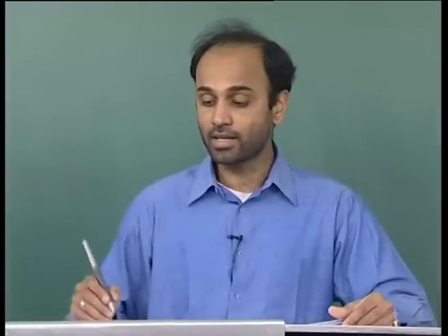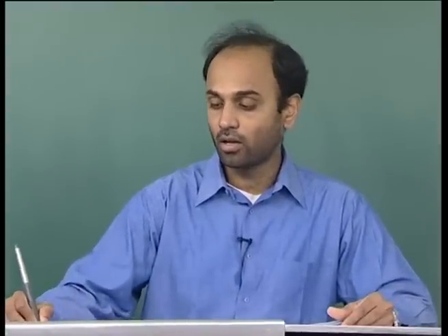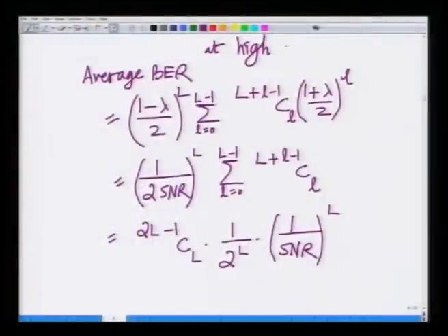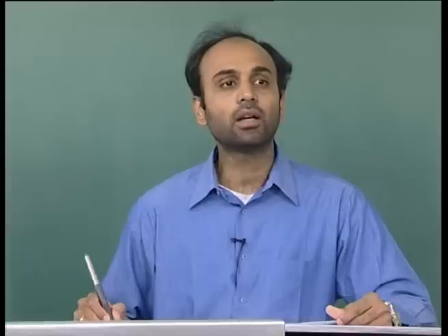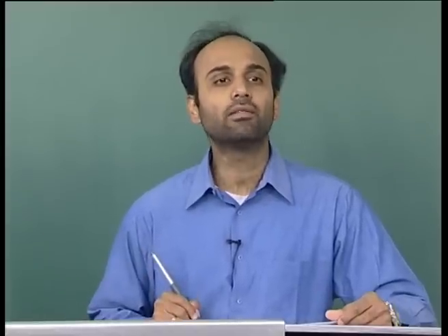Hence, the final expression for the bit error rate at high SNR is given as 2L minus 1 C L times 1 over 2 to the power of L times 1 over SNR to the power of L, where L is nothing but the number of received antennas.